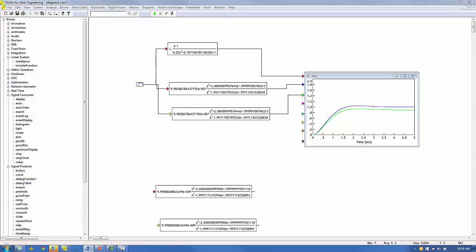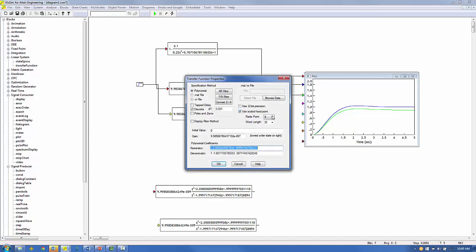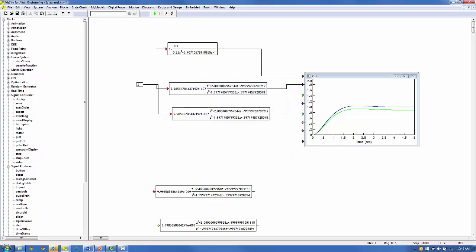Well, the transient response looks okay, but the steady-state error from the fixed point discrete filter is significant. Let's see if we can reduce this by increasing the precision with the format 2.32 instead of 8.32. Click Go to continue.